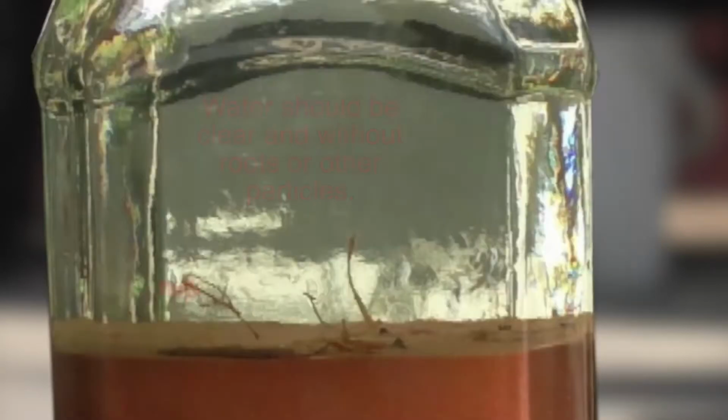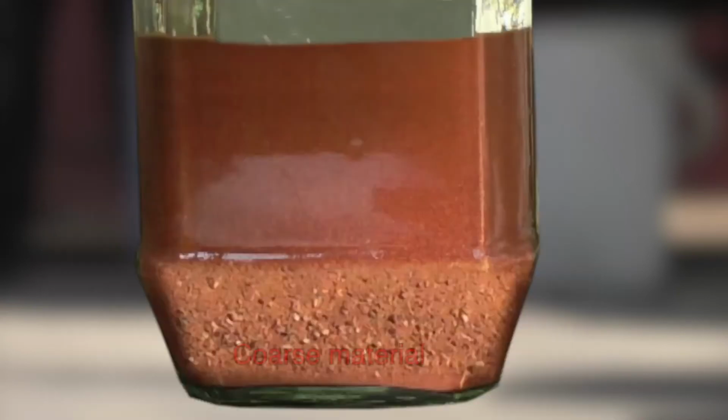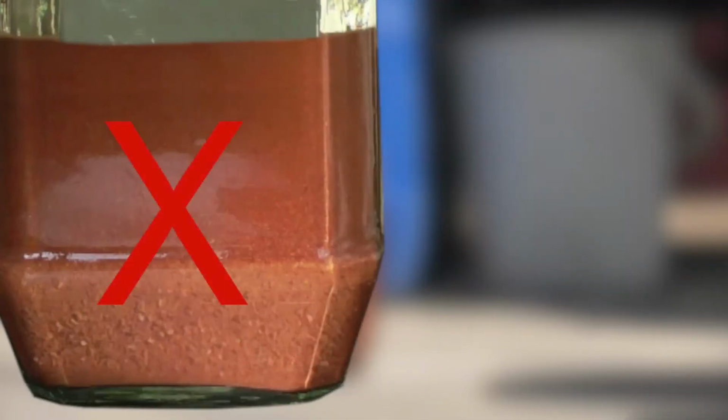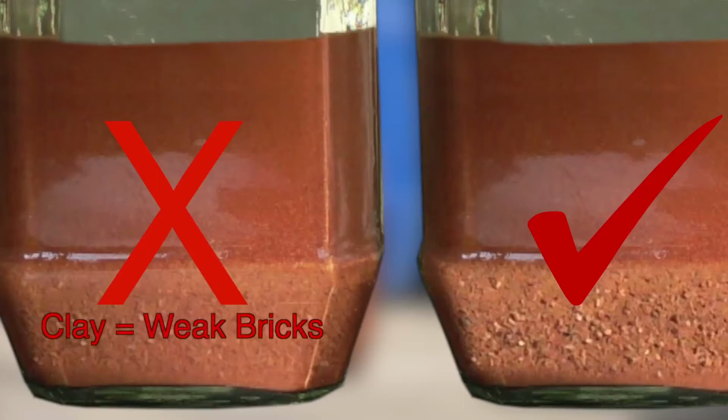The water should be clear and without roots or other particles. The material at the bottom of the bottle should be coarse, with a small layer of finer particles at the top of it. When the top layer of the material at the bottom of the bottle contains a lot of fines and only a little bit of coarser particles at the bottom, it means that the soil contains too much clay, which would result in weak bricks. This test is only an indication, and sand can be tested in a laboratory for more accurate results.